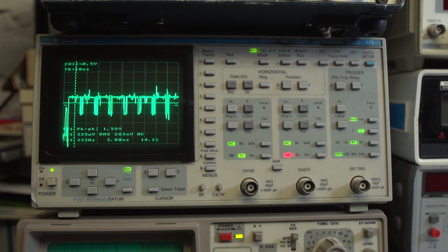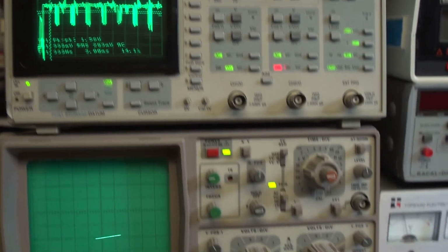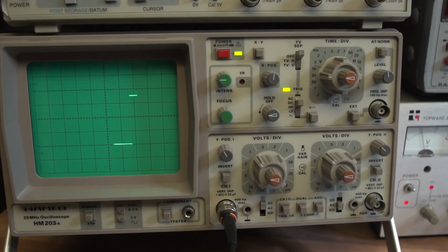So I use both personally. I have digital scopes on the PC. I use this CRT storage scope here, which is a Gould 475 model, and also a good old analog Hameg on the bottom there, which you can pick up really quite cheap, and they're very, very useful to have on the bench. I use mine almost daily for repairing audio circuits like amplifiers, digital circuits for looking at data bus activity, and looking at clock frequencies of oscillators and all kinds of things. Really very useful pieces of equipment. So if you haven't already got one, I would encourage you to get one and have a play.